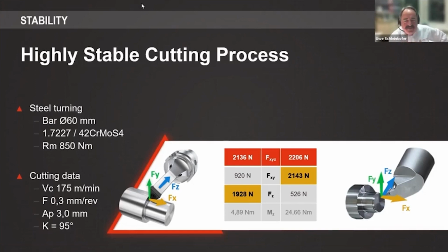Another interesting finding that we have is the torque you need to hold the tool in position, because this is also one concern when you see the FreeTurn tool: is my milling spindle able to hold the insert in position during the turning process with the torque of the spindle? And this was quite surprising.